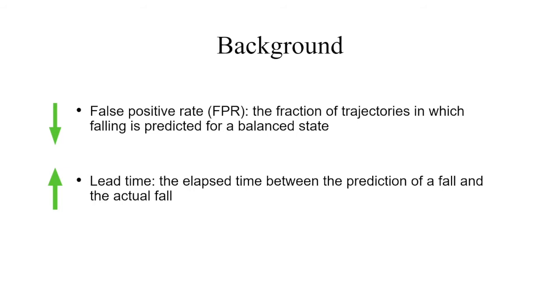However, after the force is applied on the robot, the balanced state and fall state are very similar to each other, and it is challenging to differentiate between them within a small interval by relying on instantaneous states, which is considered by previous methods. Because of the complex and potentially chaotic response of a biped to environmental forces, it may not be sufficient to make predictions using only instantaneous measurements. Thus, we proceed to use a recurrent neural network, specifically long short-term memory, to use a series of historical data to do fall prediction.